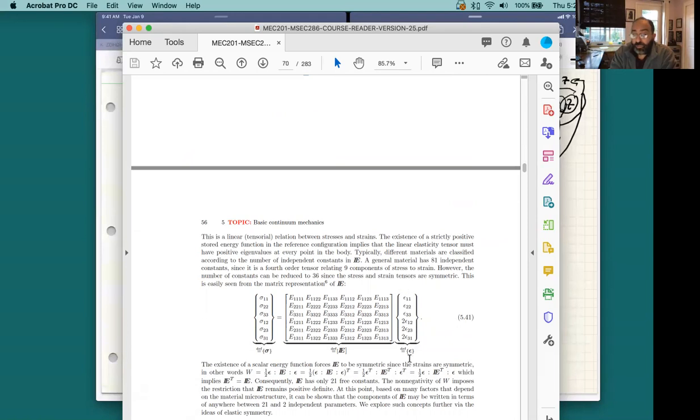We do the same thing for the strain, and we find out that this is a 6x1 vector on this side, this is a 6x1 vector on this side, we either have 2 choices. Since we have to have a 6x1 vector on the left, either this entire matrix is just simply a 1x1 matrix with one material constant. That actually was tried very early on in the beginnings of mechanics. That didn't work out so well.